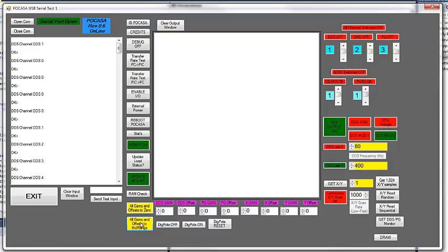And down here you preset them to 0 for minimum voltages, minimum gains. Maybe you're initially plugging something in and you just want to dial them up real slow so you can get them all maximized. And set it to mid-range. Maybe you don't know what you're dealing with. Digital pots off, digital pots on, reset. If you're at 0, you reset them, it resets back to a mid-scale.